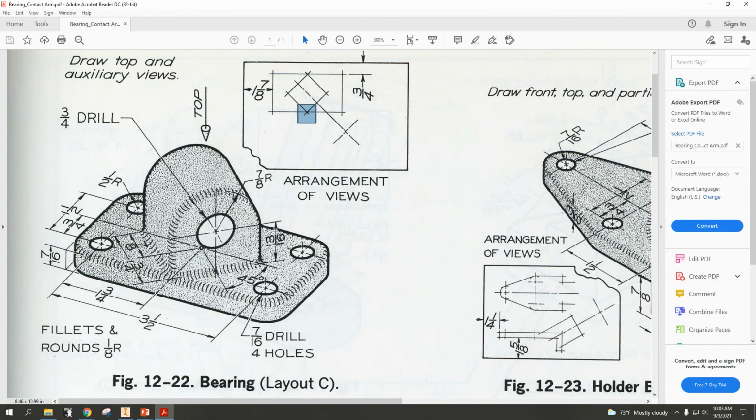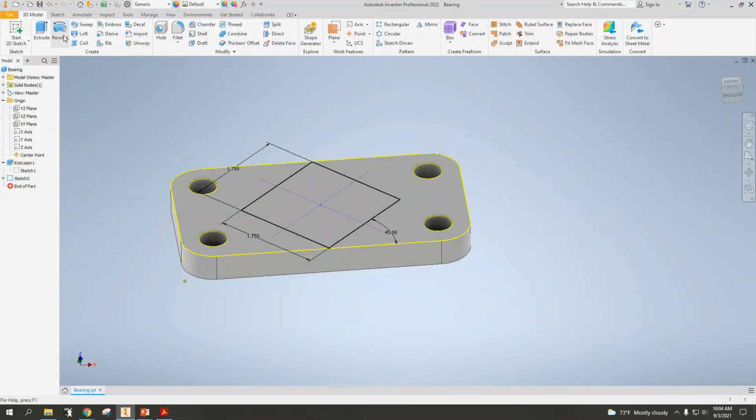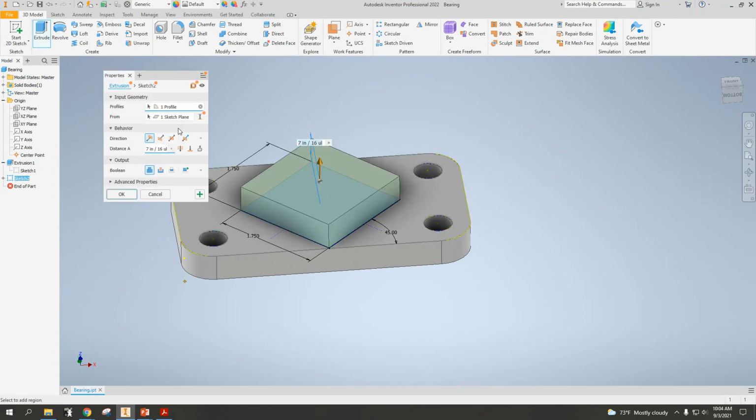Now, my head says I could extrude for a 13/16 height, but I'm gonna do a 13/16 height plus the 7/8 of an inch radius. And now you can do the math. That's gonna give me a rectangle or a cube. It's gonna give me a cube. And I like that idea right now. Again, there's other ways to probably do that. So show you this one. So we're gonna extrude that rectangle for, what was it?